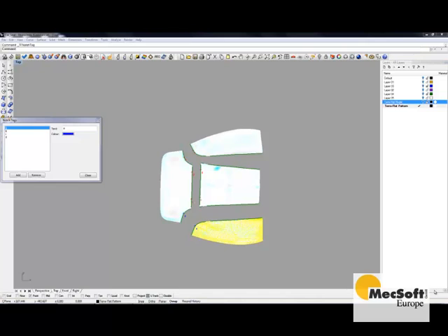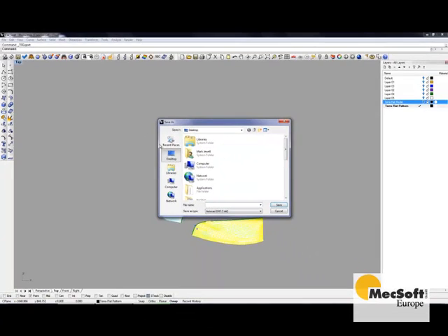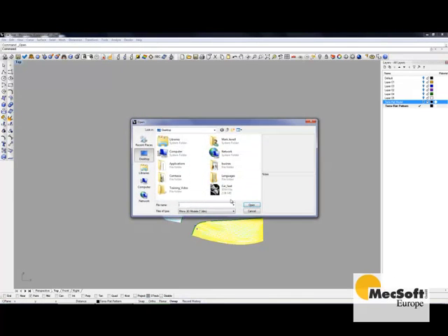Once we've added our notching information to the file, the last step is to export it as a DXF for our plotter or our cutter. So what I'll do now is simply close our dialog box for the notches, and I'll go up to this tool here, which is Export Flattened Pieces to DXF. Click on this, and we've selected DXF file, and we're going to basically create the seat from this. And let's open the file up and see what we have. So we go into DXF and go to our seat file,